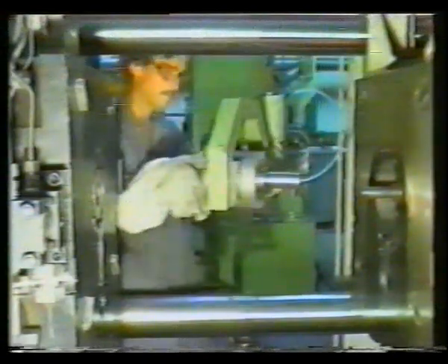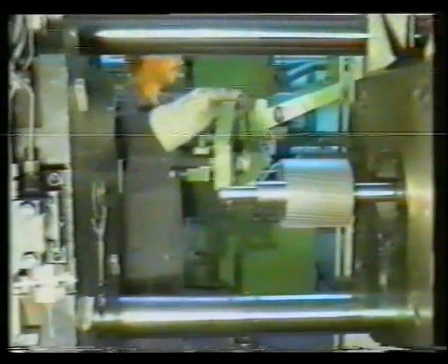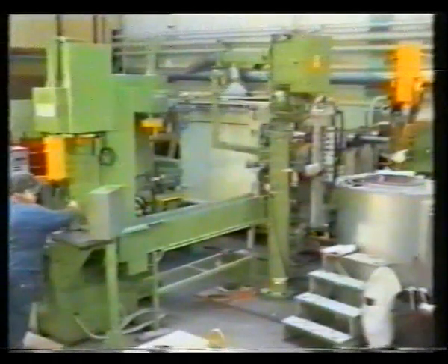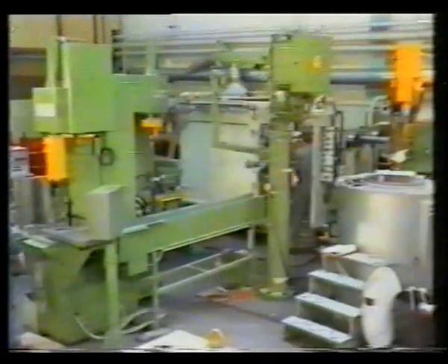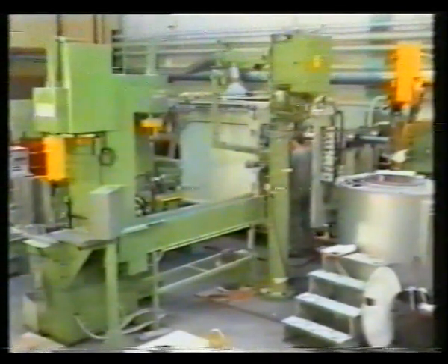An electric heating system in the die and a controlled die venting system contribute to good quality castings. Both are products of our long years of experience. The cooled mandrels, of which 10 are in circulation for each type of housing, are returned to the stacking station by a belt conveyor.